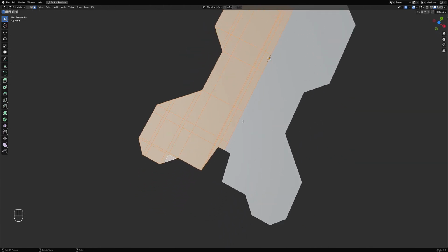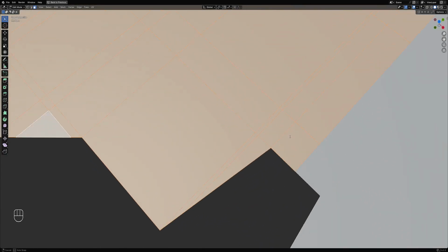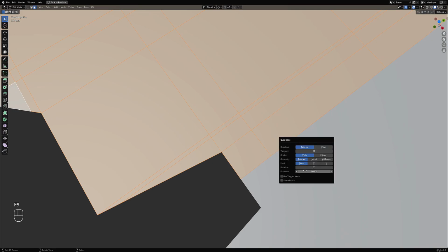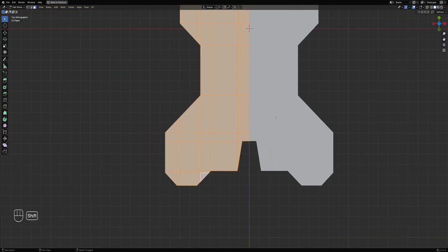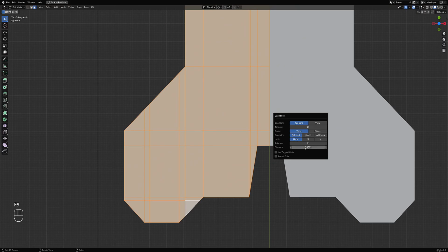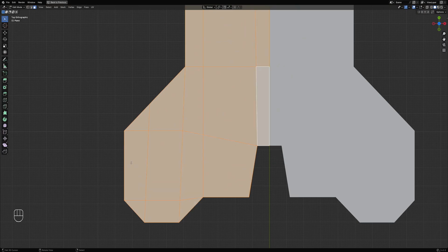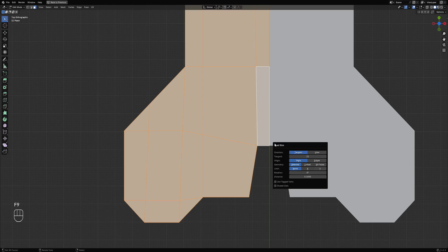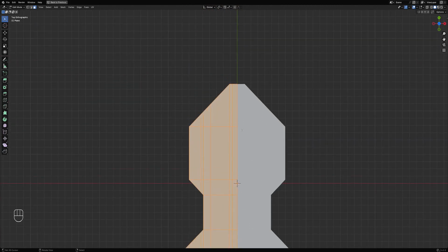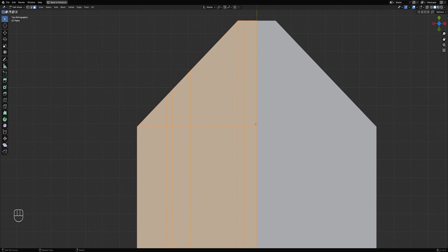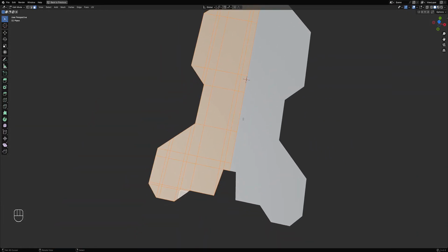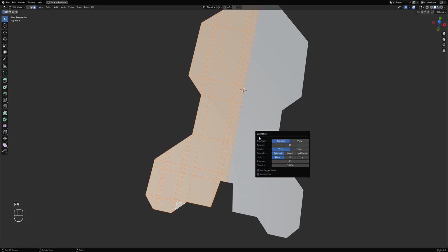Here the distance is kind of like merge. It merges the vertices or edges together, so the connections become less busy, but if you use a higher value, the lines will become distorted. Something like 0.01 for this, depending on the size of the object and the distance of the verts together. It becomes a lot cleaner than using the default, which is 0.0001.